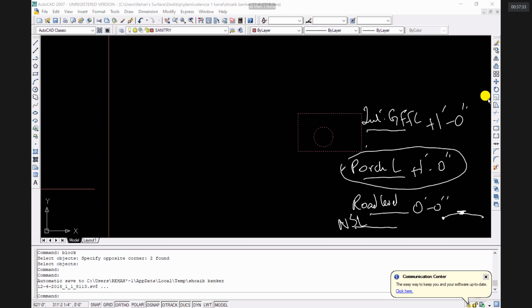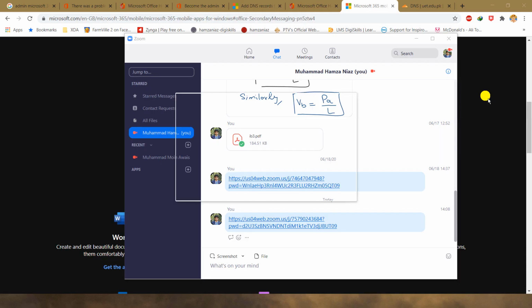The provision of beams, or creating a framing plan, is under the scope of design of structures, which you would study in the 8th semester. You decide that the wall is not coming over a wall, so we need a beam underneath it, and in that way you decide what the framing is going to be and how you are going to transfer the load. But if you understand this, you can show a beam underneath the wall.